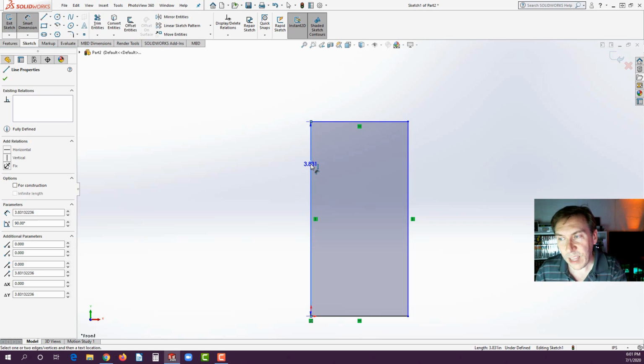Now those of you in my class that are new to dimensioning, here's the thing. Try and center the dimensions. Remember, the goal of dimensioning is to lay them out so they're easy to interpret and read. If you dimension and leave the dimension right there, when you print it out, it might not be possible to interpret what that number is. So just be aware, try and center it. Think of it like you're playing soccer or football. You have the goal and you want to get in between the lines of the goal. So we have here the extension lines, center it and click.